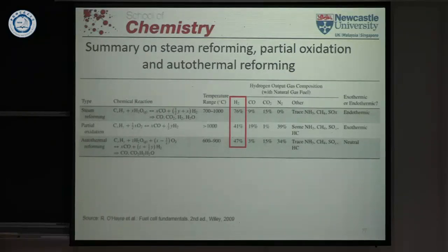In the moment you don't have that waste heat, and you really have to be aware of that, it's not only the endothermic reaction, where the reaction heat is fairly high, which you had seen, but also you add a lot of water. And you have to vaporize the water, and that needs additional heat to do this. So the overall heat demand for this reaction is really high. And you can do this only when you have a heat source that is relatively cheap, or it's waste heat.